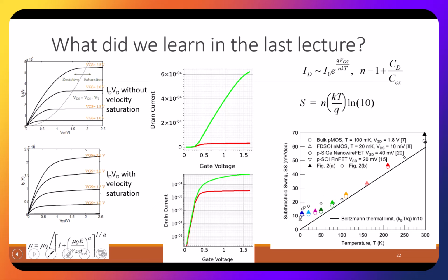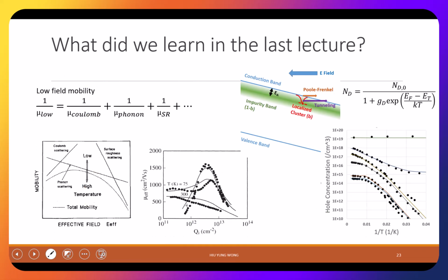We talk about band tail states and traps. And this is very important. When we say the transistor has a higher current, it's because it has a higher mobility. So we talk about Takagi's model, another important hint. Takagi's model has three important components. Try to model the inversion layer electron, which contributes to the current. What are the three types of scattering? Again, scattering is what slows down the electron, right? So what are the three types?